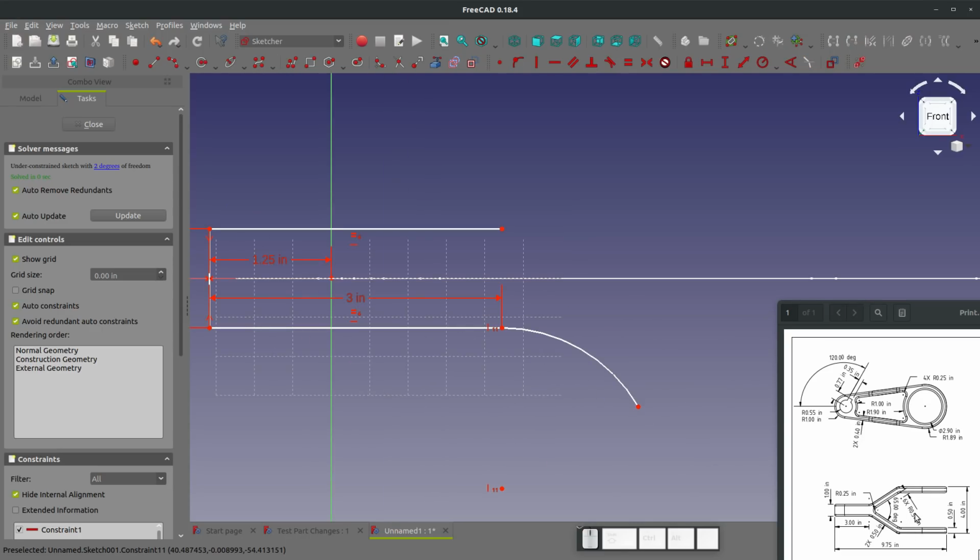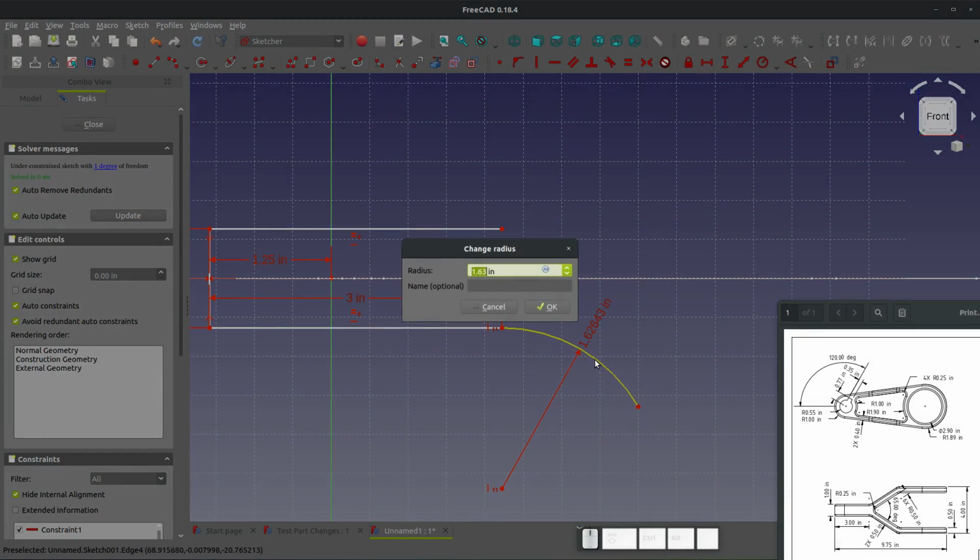Now when I made this drawing, this is not how you call out a radius, but I had to do it in this case. For some reason, all of these arcs came in as B-splines, highly unusual, and it didn't happen with other versions I've made of this part using Boolean operations. So I'm not sure why that happened, but this is kind of a funky thing that denotes radius because I wasn't actually allowed to add a radius the way you should with the program. So this is going to be 6 radii that are each 1/2 inch. So we're going to say Shift R, 1/2 inch.